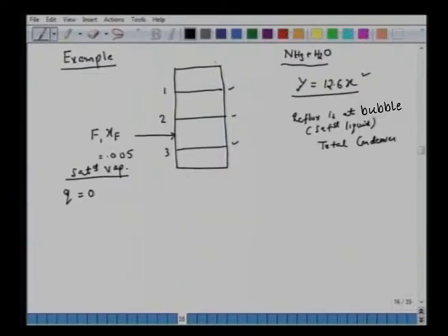Essentially, the vapor from the top plate comes to a total condenser. We have the top product with flow rate D and composition XD, and we have the reflux with composition X0 and flow rate L0. This is Y1, and the vapor flow rate is G. We have the same nomenclature. This is X0, we have L0 equal to L, vapor leaving from here, liquid dropping from here with composition X1, and this is top plate 1, so this is Y1, and this would be Y2.